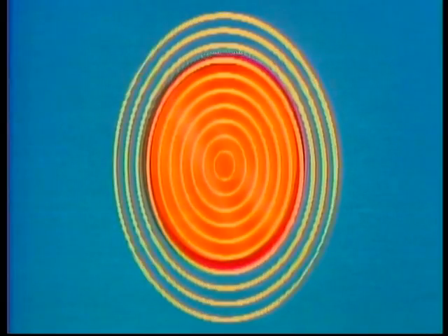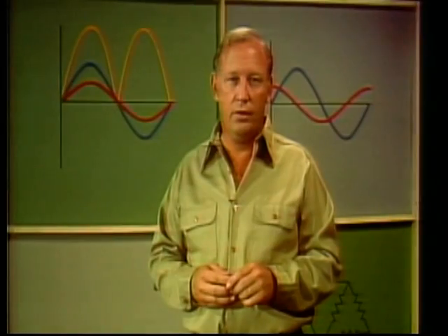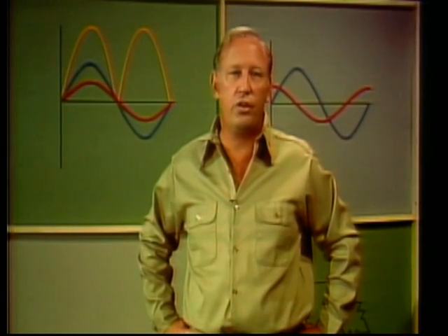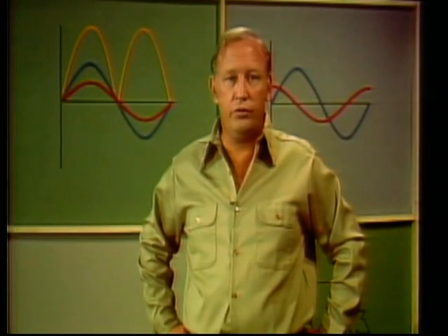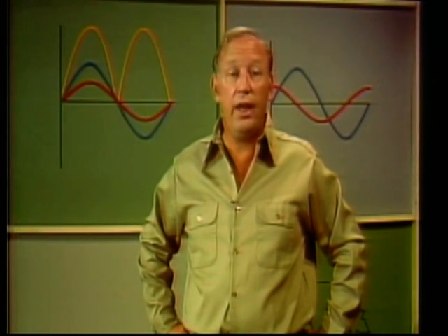When the magnetic field has collapsed completely, there is no motion, so there is no self-induction. As current starts to increase toward its peak negative value, the magnetic field builds up again. Whenever there's a variation in current, the magnetic field also varies. As the magnetic lines of flux move, they cut across the current-carrying conductor. The voltage that's induced in the conductor is always in such a direction as to oppose the current change. In other words, if current is trying to increase, the induced voltage opposes the applied voltage, and if current is trying to decrease, the induced voltage aids the applied voltage.